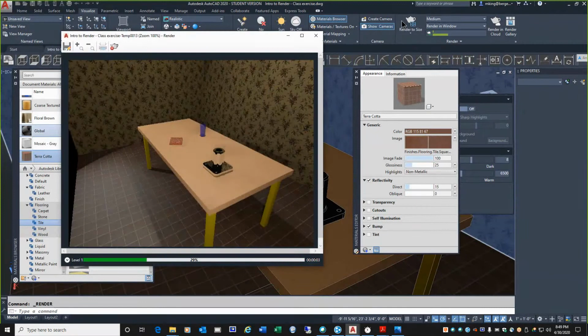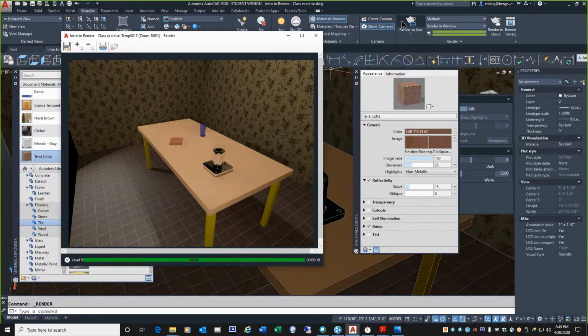Better. The scene itself is looking dark, and I'm telling you, a big part of that is because we don't have the other walls and ceiling to help trap in the light and bounce it around some more. So if we were insistent on keeping this, I would go to that exposure control and I would nudge it down a little bit. But here's what I want to do.